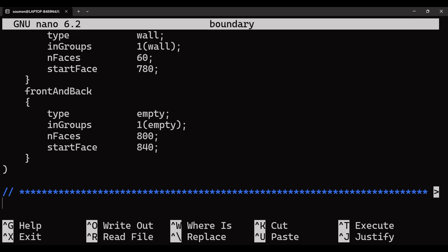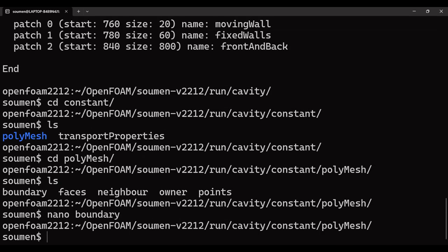Please note that by default OpenFOAM is 3-dimensional, so it does simulation in a generic manner in 3 directions, but if you have to do 2-dimensional, you have to prescribe empty boundary conditions in the direction that you want to restrict the solution from being calculated. Okay, that's it. We have now created the mesh.